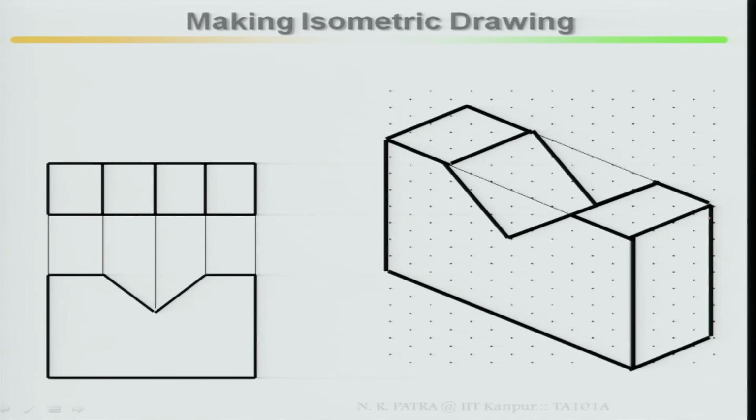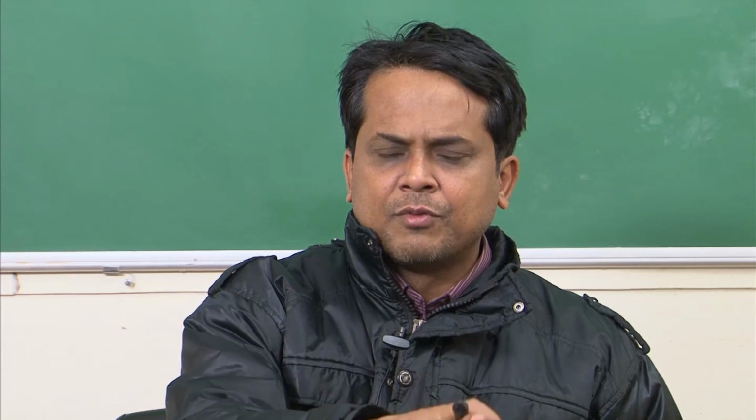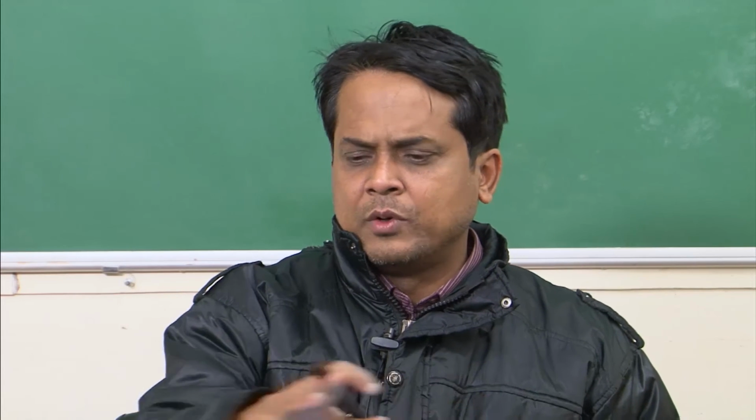With respect to this, if I take a front view from this side, whether this is correct or not, whether my front view is the same or not, viewing direction. If I am looking at the top, third angle projection, whether my top view is looking like this or not. Once these are the same, whatever views have been given, front view and top view, with respect to that your isometric view is the same, that means your drawing is correct.